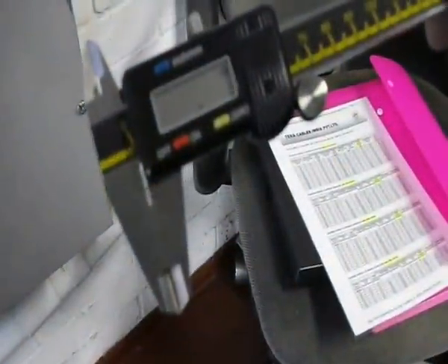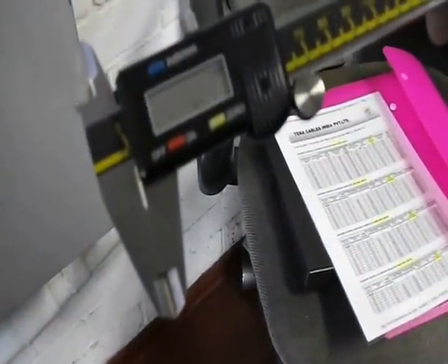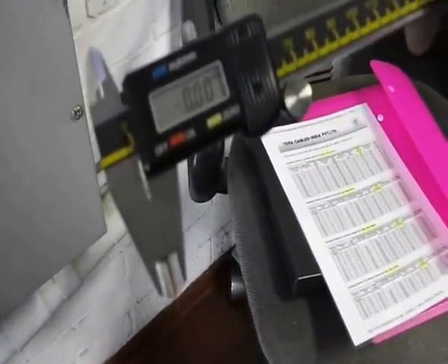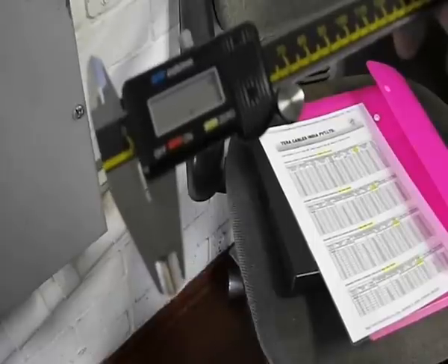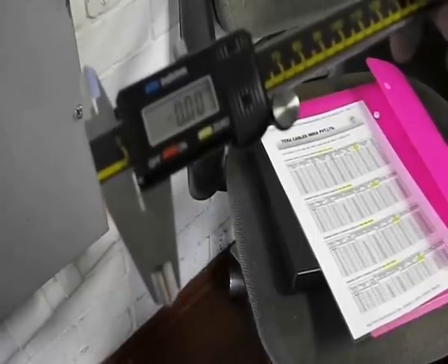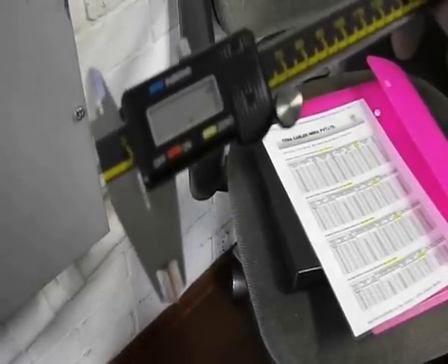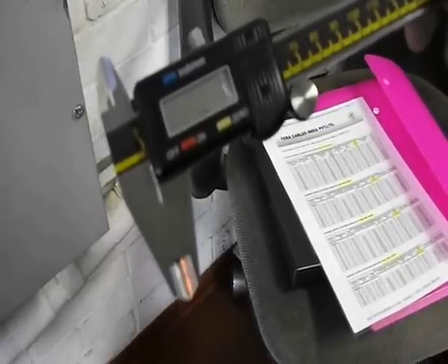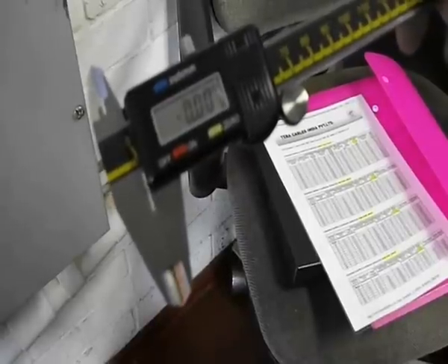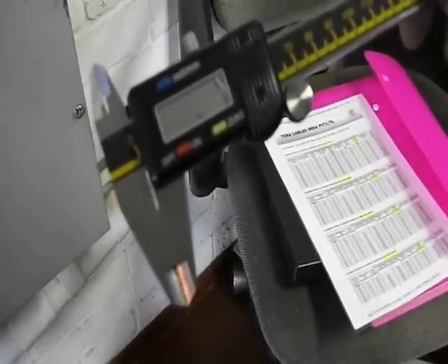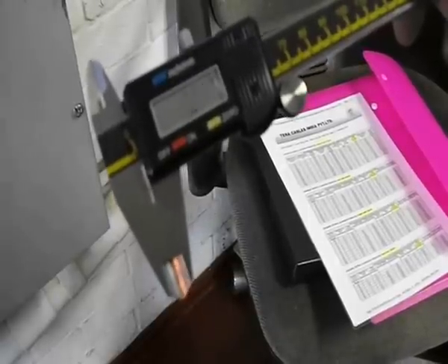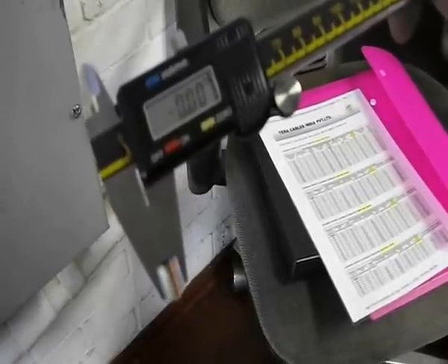I need to find out the cross-sectional area of a 4-core armoured cable, which is supplying an adjacent distribution board, and to do that I'm going to use this vernier gauge, measure the outside diameter of the cable in millimetres, and then I'm going to refer the value recorded to a data sheet which will give me some idea of the size of the cable.